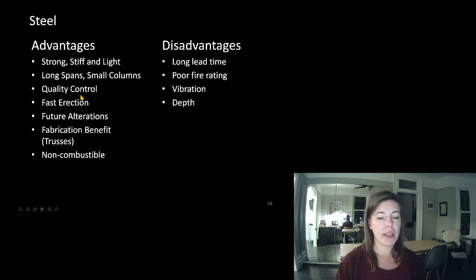Steel has really great quality control, both in the material and in the construction. So the material itself has chemists sitting there testing every batch of steel. So when we say that we have 350 MPa steel, it's a pretty tight range. They have very specific guidelines. It can only go down to, I think, 340 as a one-off batch, and the statistical probability of being in that is low. So a specific plant can only make so many in a year that are that low. And then it can go up quite a bit higher.